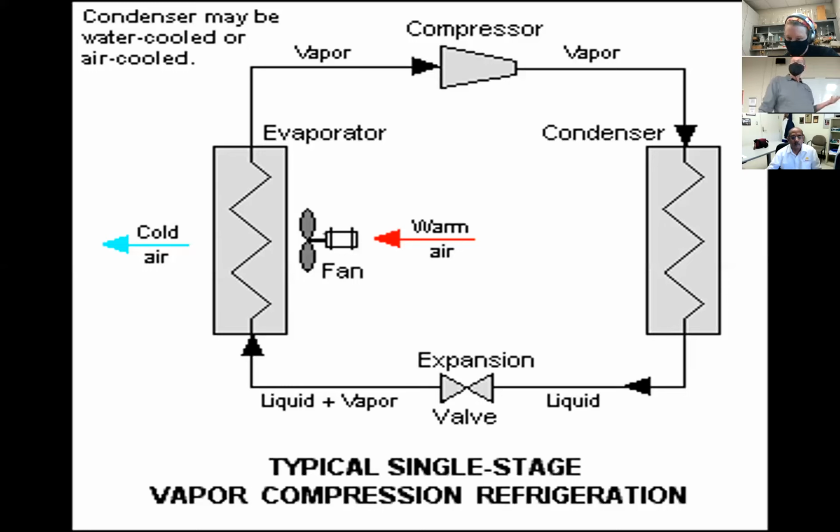Now, one thing to think about, because I've been known to ask a question on the take-home final: why can't you just go from Freon to ammonia in here, or ammonia to Freon? It's all sized, right? The amount of volume that will go from liquid to liquid vapor and eventually to vapor in the evaporator, it's going to depend on the pipe, how much the flow is through there.